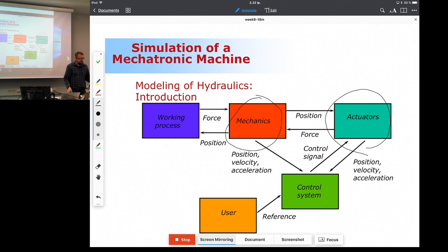But a problem associated to hydraulics is that it still suffers quite a bit in energy efficiency. Hydraulics is quite efficient when you look at the efficiency of the pump or the efficiency of the hydraulic cylinder. Those are components where the energy efficiency is very high. But as a hydraulic system, as a simple entity, the energy efficiency may not be very high. That's simply because of the design of the pump. Roughly speaking, the idea of the pump is to keep on producing energy to the system, and it will do that regardless of whether there's a need for energy or not.